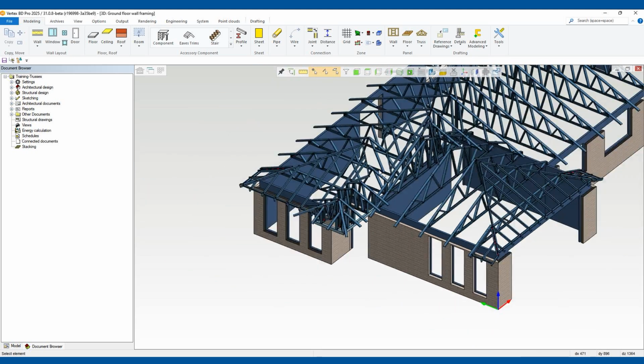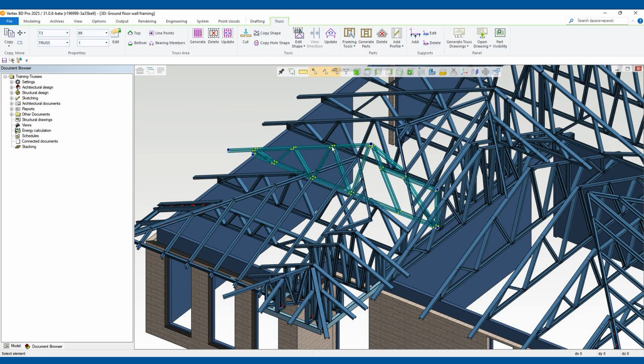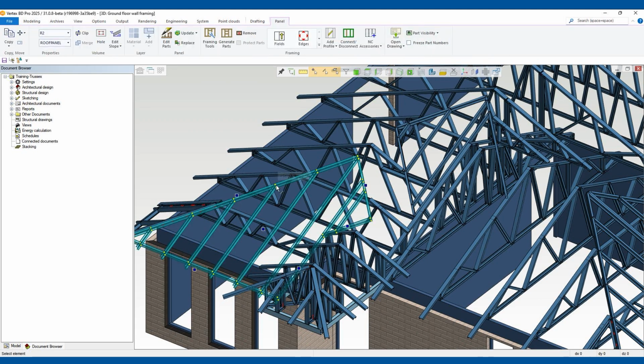Another thing I should mention is that truss engineering is just for trusses, just these main trusses. It does not engineer these roof panels. We do an FEA study on them. So roof loads get transferred to the trusses, etc., but we're not doing a pass-fail as such.